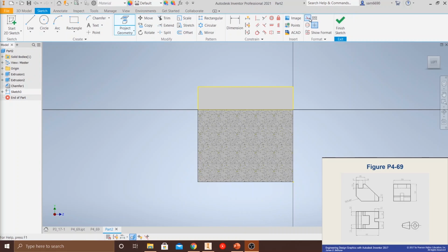So what we're going to do is come over here. We're going to take a construction line, make our lives a little bit easier. We're just going to create a construction line right across here, 12 millimeters. Let's do the same thing for the other side, 12 millimeters. Okay, so now we know that in between these two spaces is the length that we need this cut to be. We also know, based off of this left view, that it goes all the way to the top.